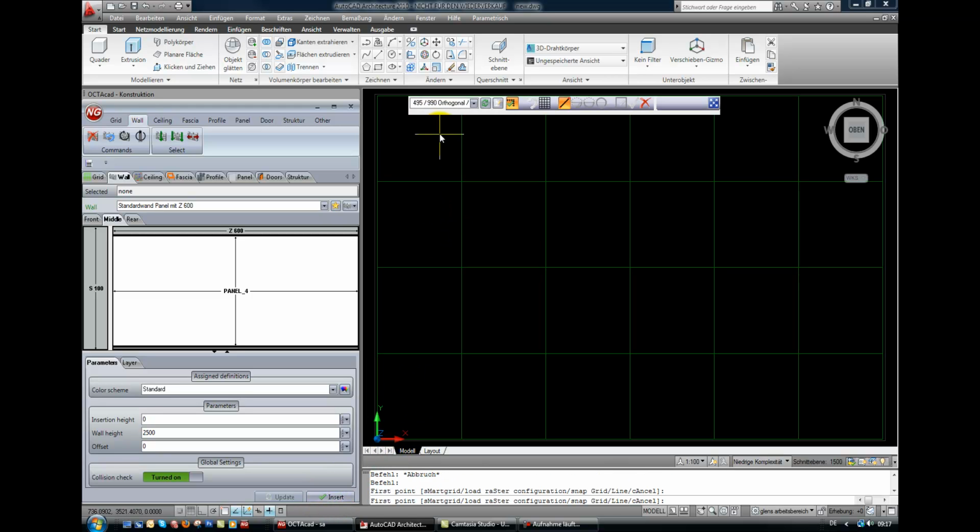and then the ribbon bar with the construction options appears. Here I can give the different lengths of the walls I want to construct, and this button here is very useful too. It's the Smart Grid button, and it means that if it is turned on, you can construct in your given sizes. If it is turned off, you can construct free sizes of walls. So I will start to construct now.